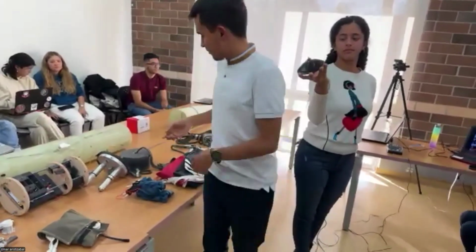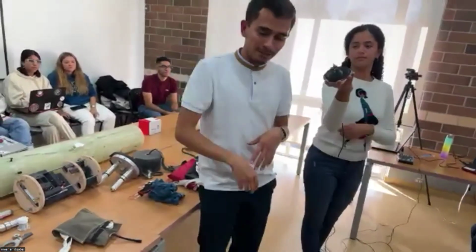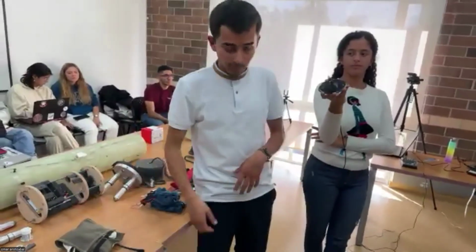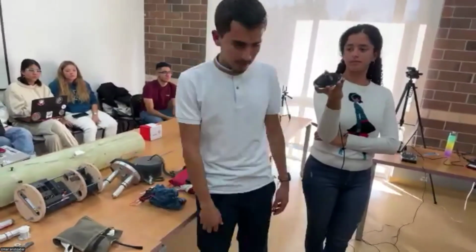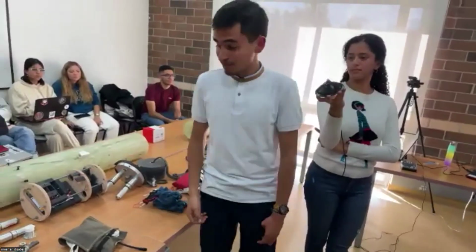The shock cord should not make the nose cone collide with the other section of the rocket when deploying the main parachute. That's why we have a 35 feet main shock cord.